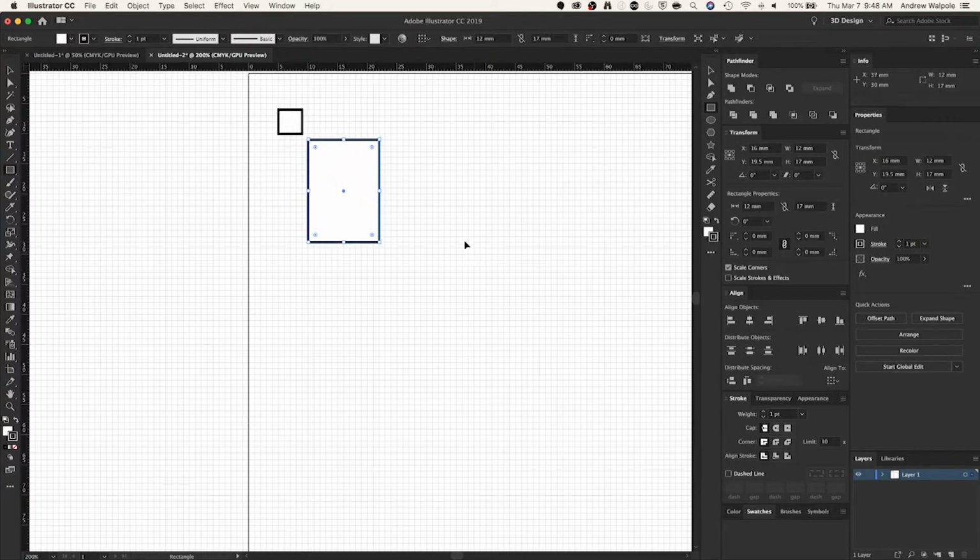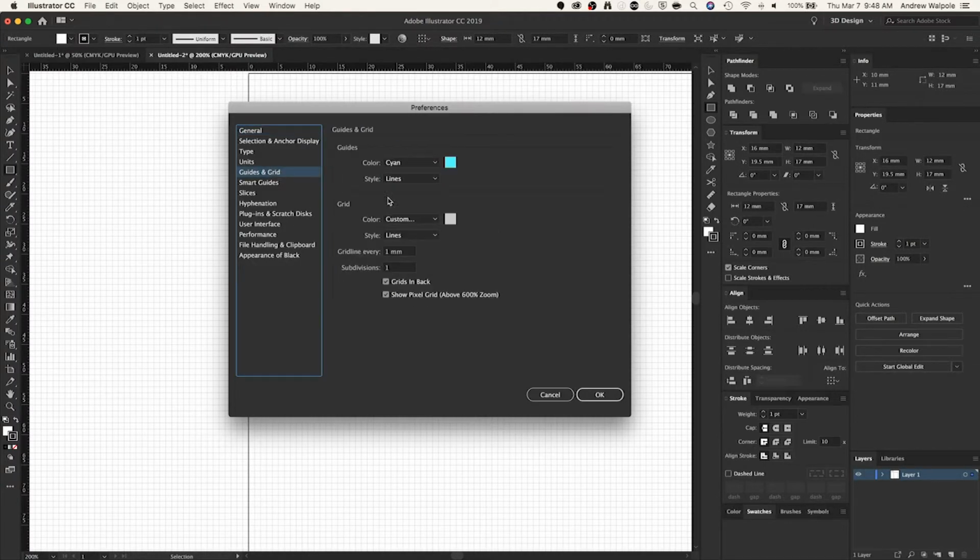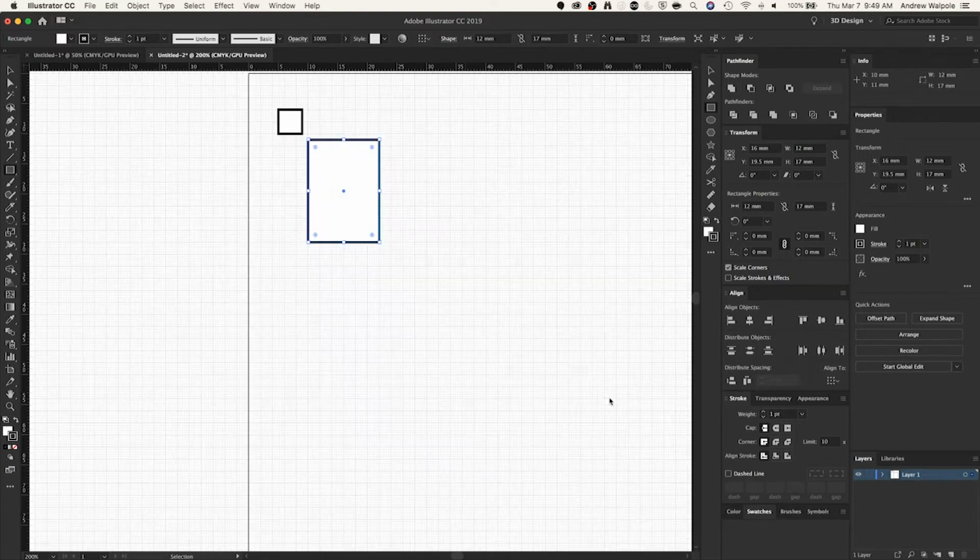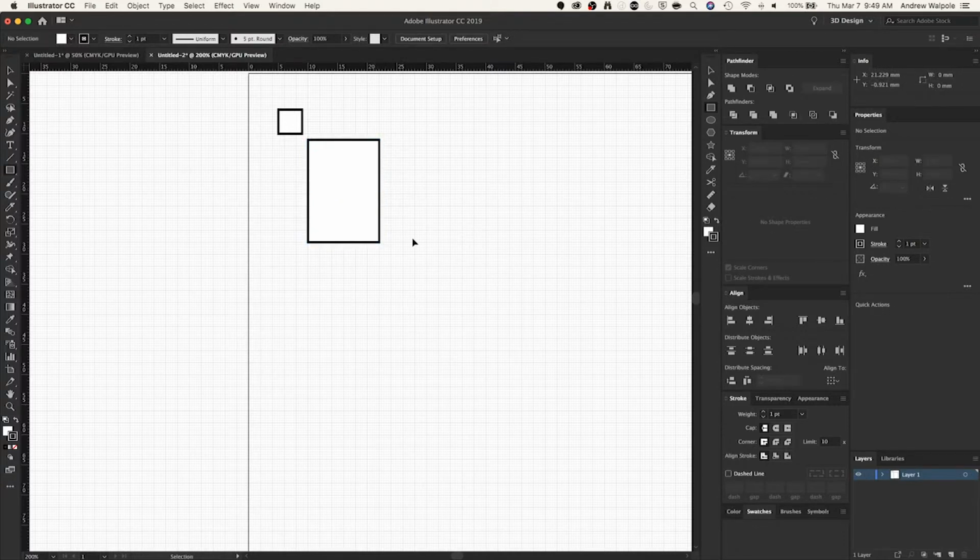Now we can go back to that grid definition, and maybe you're not dealing with really big parts, you're actually dealing with smaller increments of millimeters, which is probably more common for 3D printing. Maybe you want every 0.5 millimeters or every 0.25 millimeters or every 0.1 millimeter, which is a really nice, round, granular way to look at things. And so I can change the subdivisions from 1 to 10. And now the darker lines you see here between them, that's 1 millimeter.